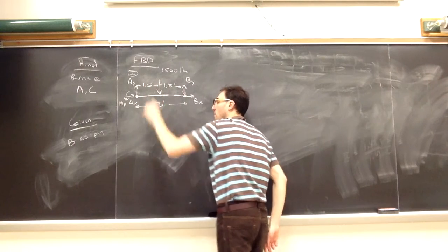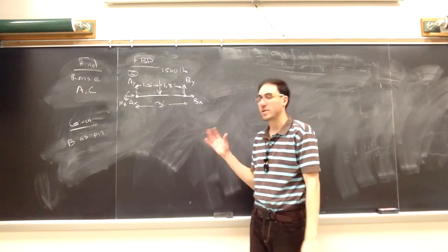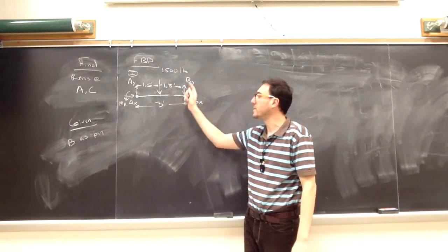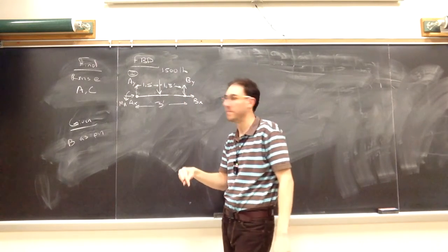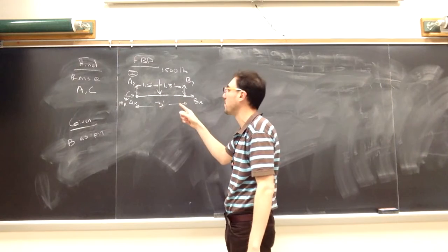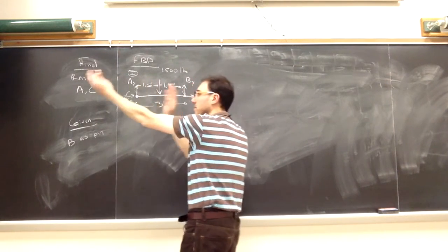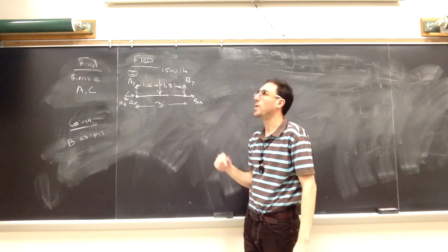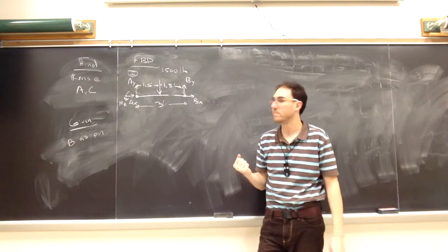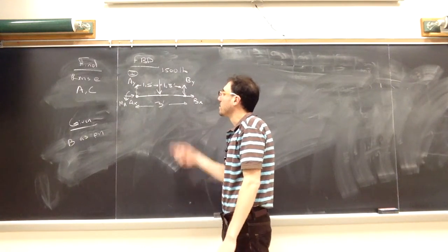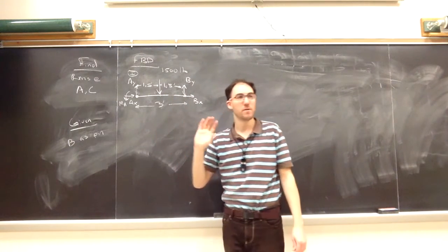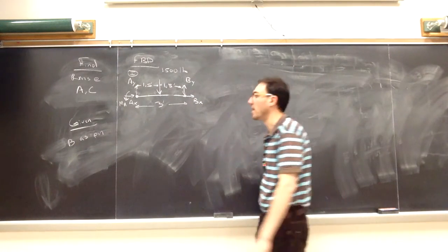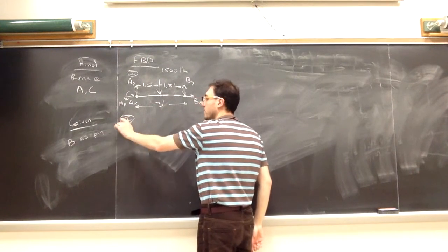And this is important for finding our supports. Also when we get to the internal drawings, when we draw a cut segment, that segment only sees the distributed load that directly touches it. So in this case, it was 3 feet of that distributed load. Again, if that was sand and we separate it out, we're replacing that with an equivalent point load at the centroid with the 1,500 pounds of force. So this is the simplified picture for just segment AB. We have 5 unknowns here, so I'm going to move on to my second picture before I attempt to write any equations.